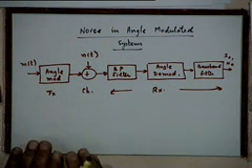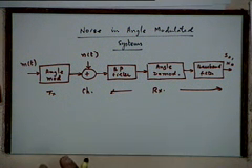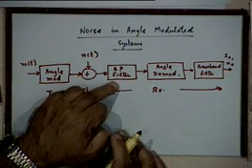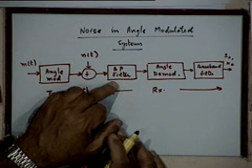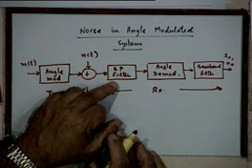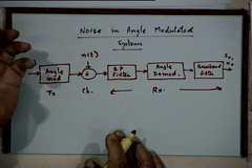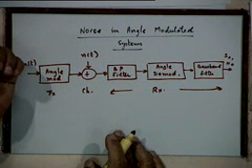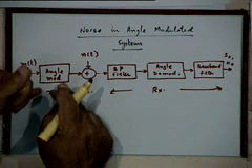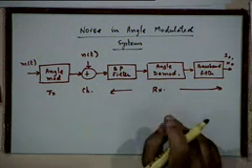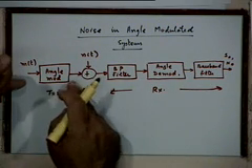Before we proceed on to the calculation, just a couple of remarks to keep in mind. We can't exactly proceed the way we proceeded for amplitude modulation for two reasons. One is that the band pass filter here has a very different bandwidth as compared to the band pass filter that we had at the input to the amplitude demodulator. Do you appreciate that? Because your angle modulated signal has a much wider bandwidth. Of course, we are considering a wideband FM, isn't it? It has a much wider bandwidth.